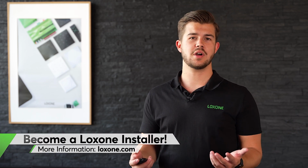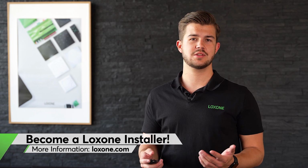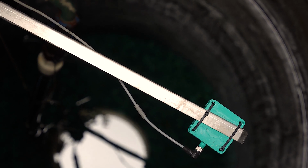The irrigation function block, available in version 12.1, saves you the time it would take to configure a custom logic and ensures a clean and clear configuration. But of course, the configuration can still be extended with your own logic and adapted to the individual needs of your customers. One example of this would be to monitor the fill level of the rainwater tank with the help of an ultrasonic sensor.